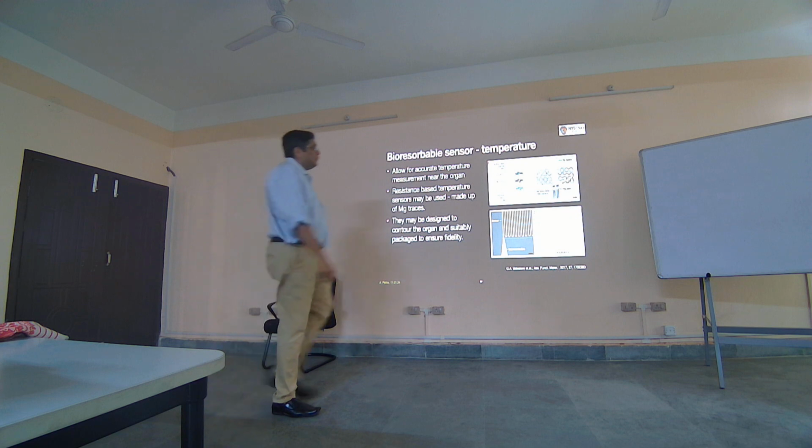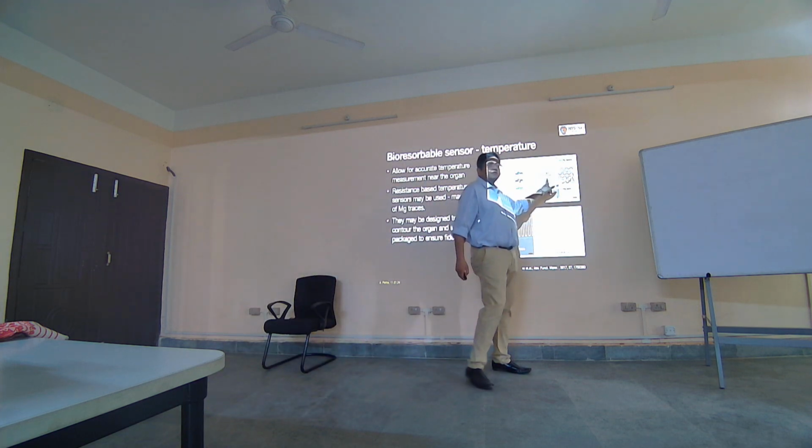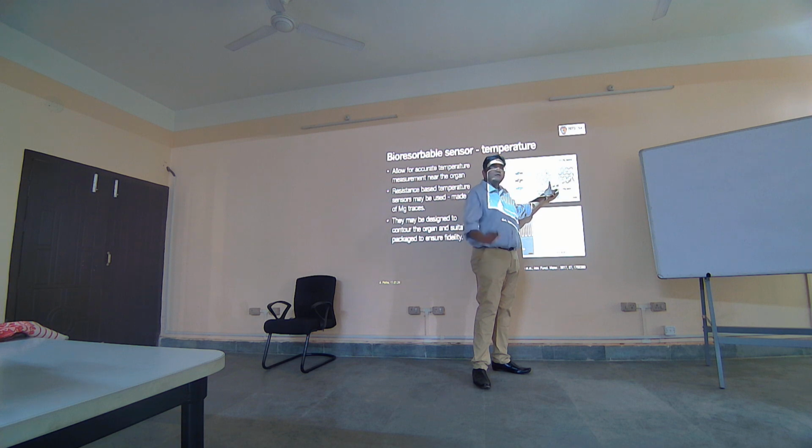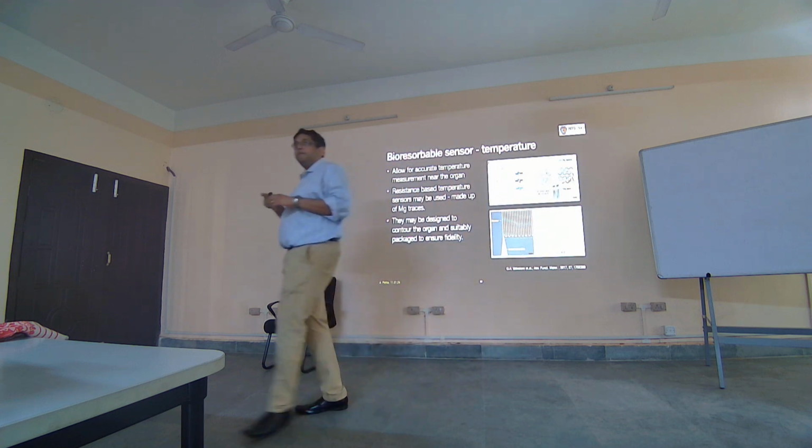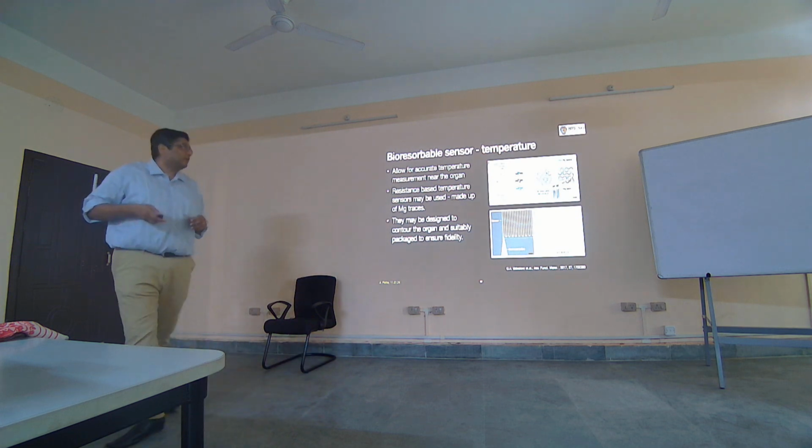And the reason we do these kind of weird funky features is because, one, we want a lot of material, because that's when the resistance will respond. So you want a long line, but you don't want a large aspect ratio. Second thing, this has to be flexible, so this should be able to bend. So that's the reason why you see these funky images here. You want that so that it can be contourable and at the same time able to measure temperature.